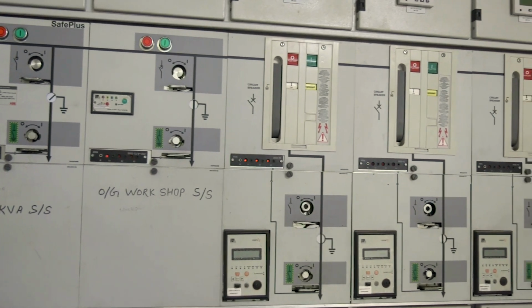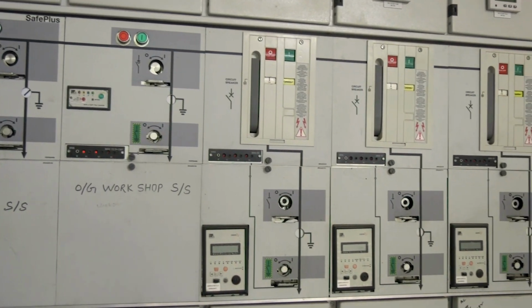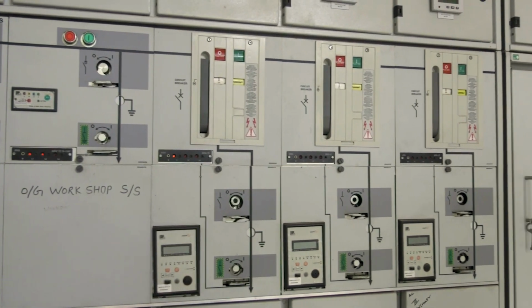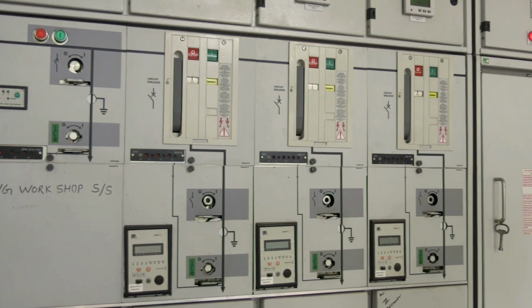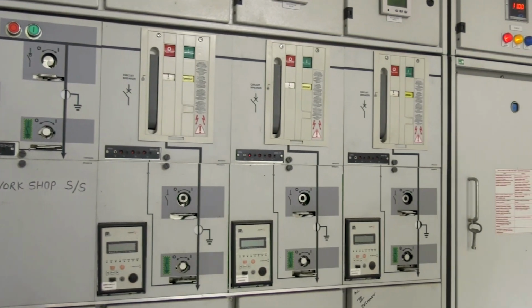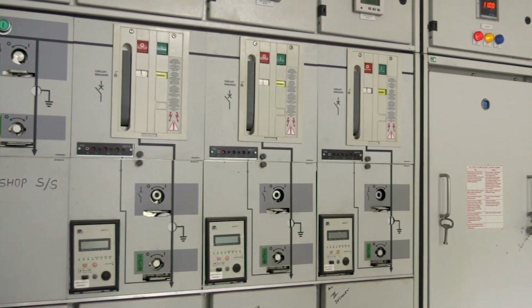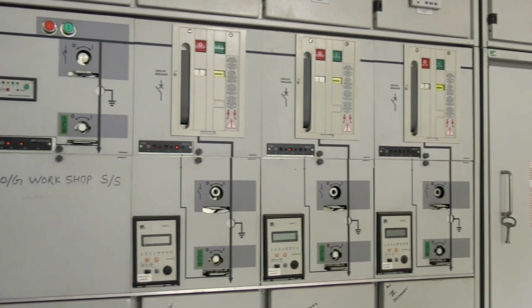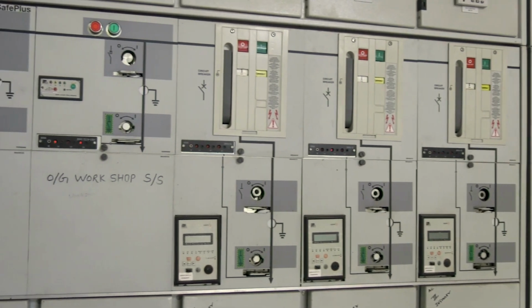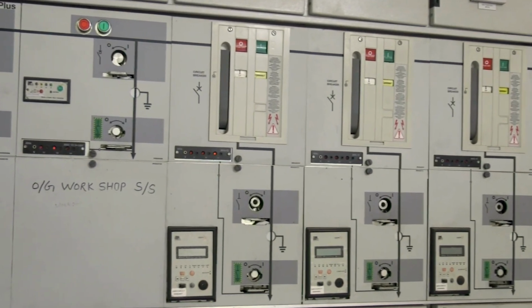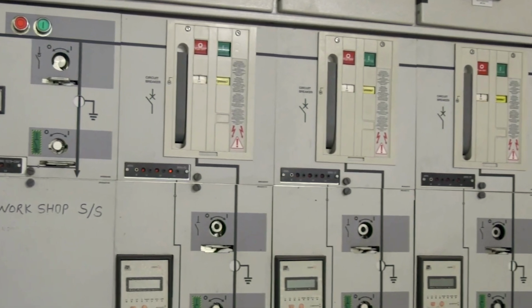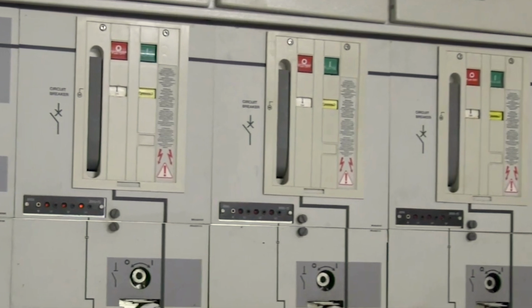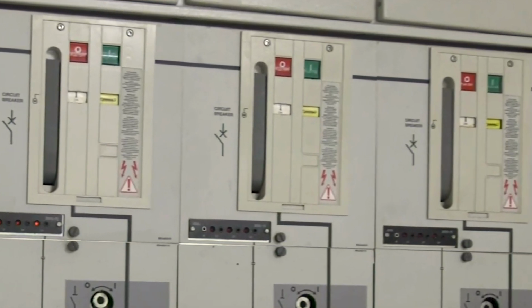Moving rightwards, the initial segment showcases the outgoing 11 kV line dedicated to supplying power to the workshop, ensuring a reliable energy source for this essential facility. Adjacent to this segment, three lines extend towards transformers, playing a vital role in stepping down voltage levels for subsequent distribution. Each of these three lines is outfitted with an air circuit breaker, which is indispensable for fault current interruptions, thereby safeguarding the system's integrity and reliability.